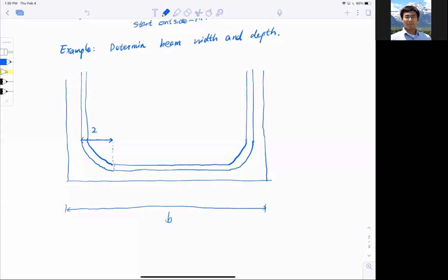And this bending radius of the stirrups is 2 times ds. So you may ask, what is ds? Isn't it the effective depth? Well, in this lecture today, ds is the diameter of the stirrups. Sorry about the confusion, but I'm running out of names.